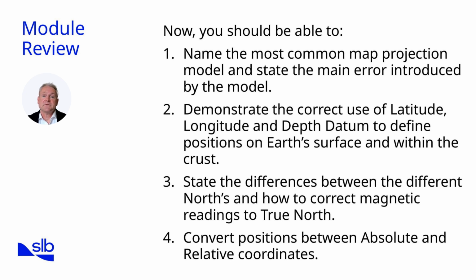Fourth, we practiced converting positions between absolute coordinates, like UTM, and relative coordinates tied to wellheads. Finally, we examined vertical reference datums and their importance in ensuring consistency across datasets. Together, these skills form a toolkit that allows you to interpret, communicate, and apply geodetic principles effectively in oilfield operations.